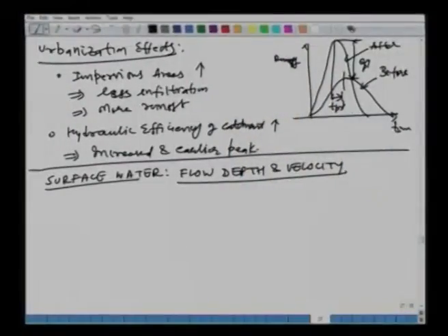So, the surface water or the overland flow is also called the sheet flow. It starts to move very slowly initially, and then the velocities become higher, and then the water will start to move into very small channels, or these are called the rills. After some time, these channels will combine into bigger channels, and then bigger channels will finally get into the rivers and streams. Okay. So, this is the process of conversion of your effective rainfall to the flow in the rivers. Let us look at it briefly, and then we will go to the mathematical modeling.